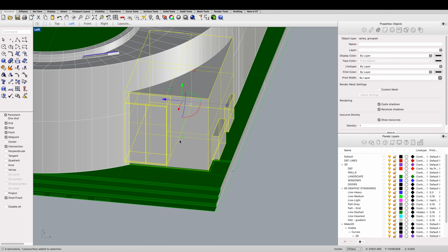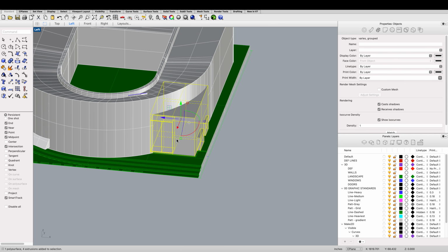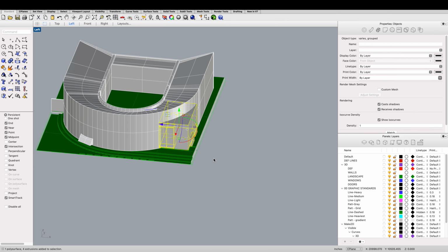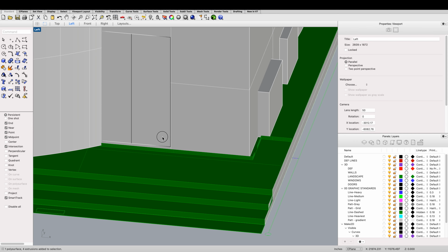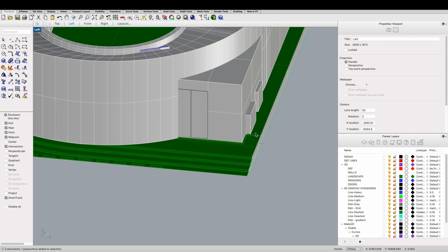For the doors, I did a Boolean split. This one's pretty dumb. You can just make some boxes. Did you inset the door? Yes. So I inset the door, and what's on the inside doesn't really matter because we're not doing the hidden lines. I mean, if you want to try the hidden lines, we can try that.